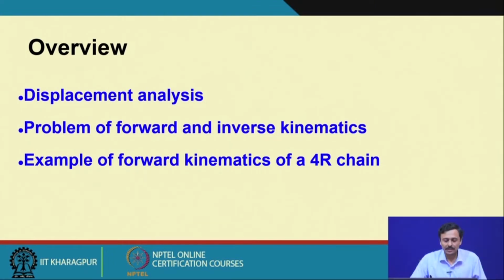This problem is known as the displacement analysis problem. We are going to define and look at the problem of forward and inverse kinematics. So, displacement analysis has these two problems, forward kinematics and inverse kinematics, and we are going to restrict ourselves today to the forward kinematics of 4R chains.